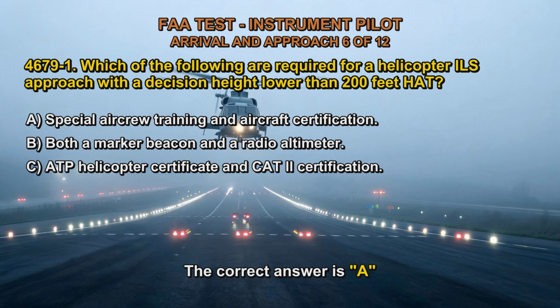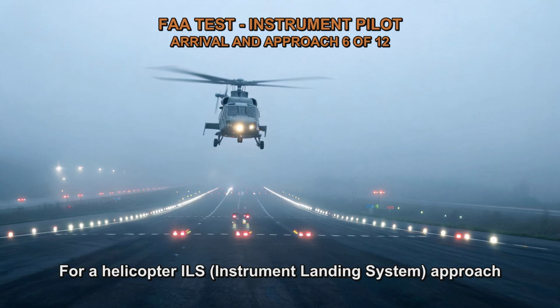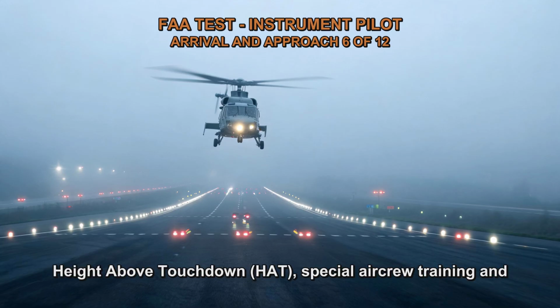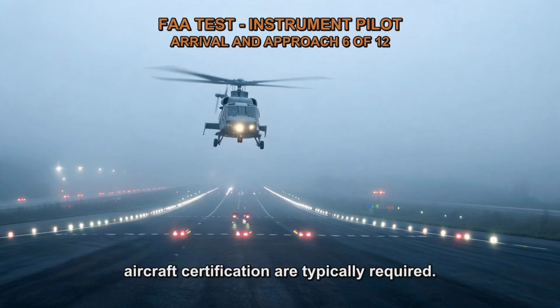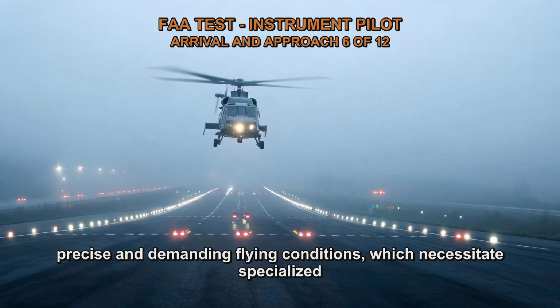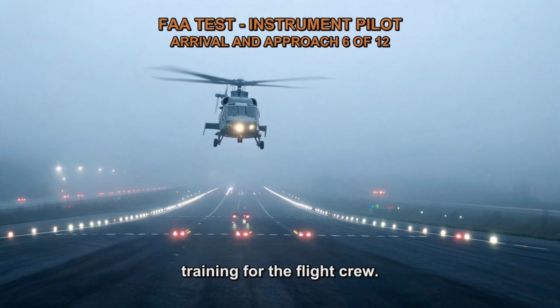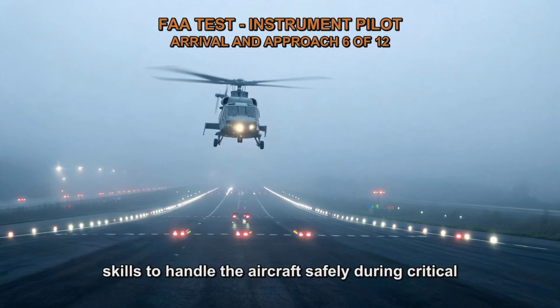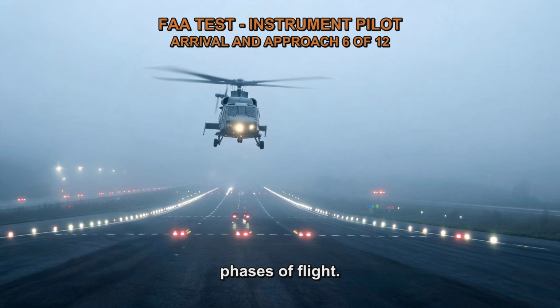The correct answer is A. For a helicopter ILS, instrument landing system, approach with a decision height lower than 200 feet height above touchdown, HAT, special aircrew training and aircraft certification are typically required. ILS approaches with low decision heights involve more precise and demanding flying conditions, which necessitate specialized training for the flight crew. This training ensures that the pilots are proficient in conducting the approach and have the necessary skills to handle the aircraft safely during critical phases of flight.